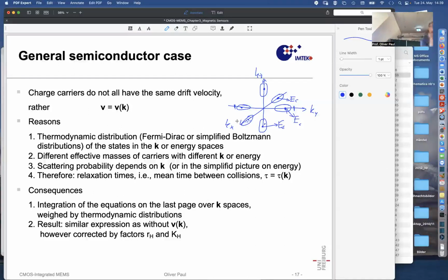And they do so for 2 reasons. First, they can collide with impurities in the semiconductor. The dopants are impurities, and the more impurities there are, the higher the doping, the more strongly they collide, the less long they can propagate uninhibited.